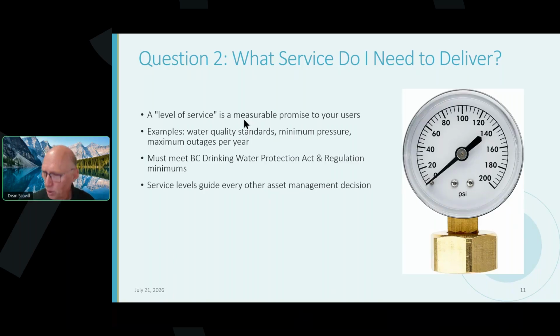It should be fine. So the operational staff were saying, hang on, we've got to do this slowly because we have a lot of experience in the field, right? Anyway, the engineering staff went ahead, cranked up the pressure, and all of a sudden we had these phone calls: my water service just blew. They had old, say, copper plumbing or old polyethylene type service, and it's just brittle. When you crank up even 10 psi, it can cause some damage. So there had to be a little bit of repair work going on. When you increase pressure, we've got to make sure our service connections are tight and not old, right? Again, that's knowing your assets.